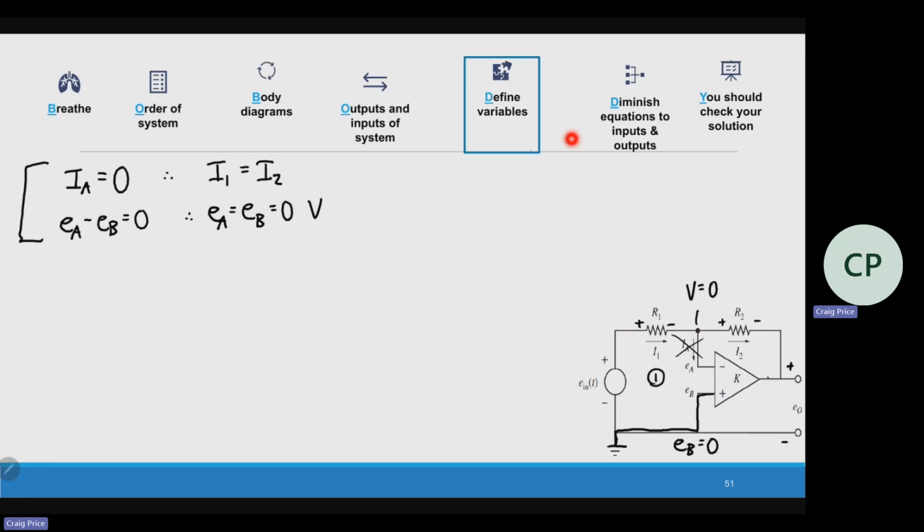For this loop and this loop, we do want to set up some kind of KVL. Now, I would call these partial KVLs. This looks incredibly complicated. I don't think I'm going to go all around the loop because then I have to go through the op amp. Same thing with this. But because of our op amp rules, I know that this point right here is 0 volts. And I know that once it gets to that node on top, the voltage is equal to 0.